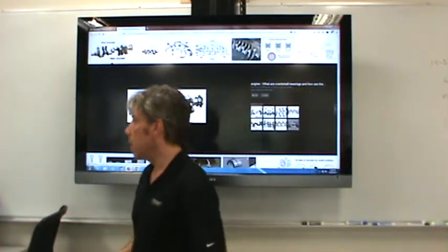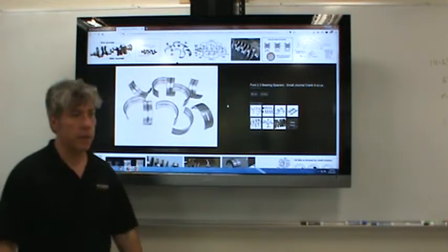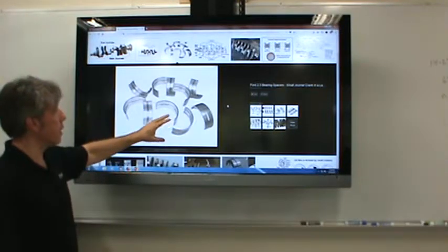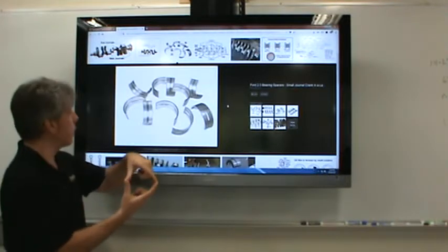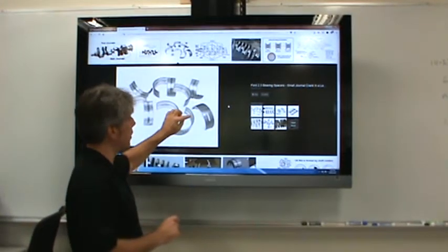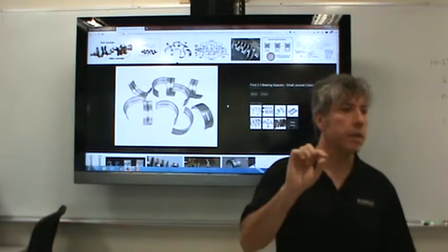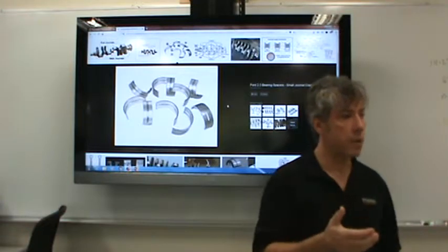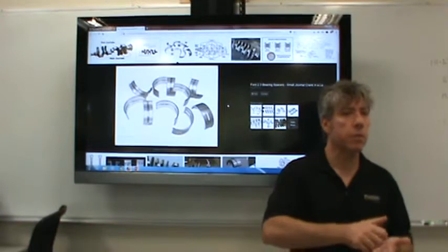Now, if you replace the crankshaft in your car, if you ever pull it out, you'll probably put these in. Have you guys seen these before? You know what these are? Okay, well, these are the bearings themselves, and they go around each journal. The way it works is there's a very small difference between the inside diameter of these bearings and the outside diameter of the journal, and that little bit of clearance is, I don't want to say filled by oil, but oil does go into that clearance, and that's what keeps the journal surface from touching the bearing.